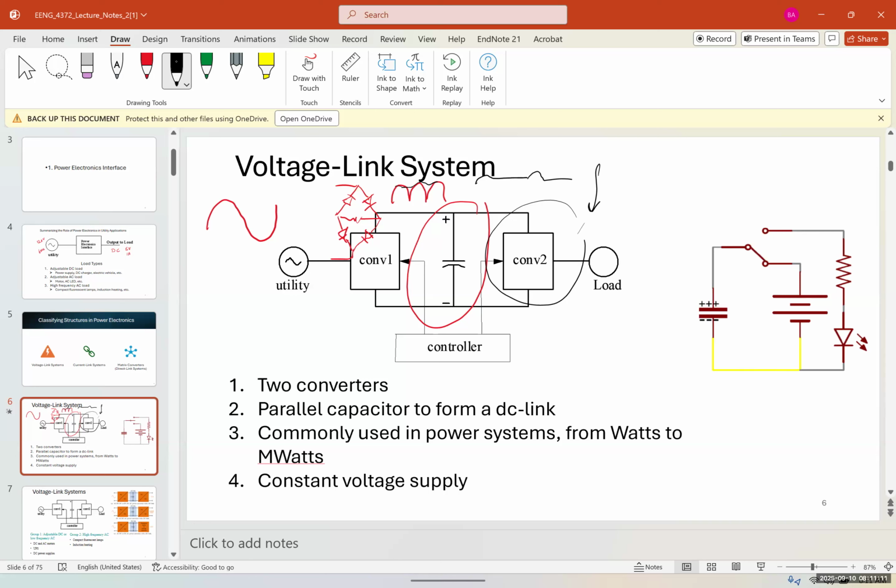So what it could do, it could increase the voltage or decrease the voltage. So imagine this is 5 volts. I'm sorry, let's make it 120 volts. 5 volts is too low for this. And then this is a buck converter, and I'll explain a buck converter, and it's a filter, and it reduces that to 5 volt DC.